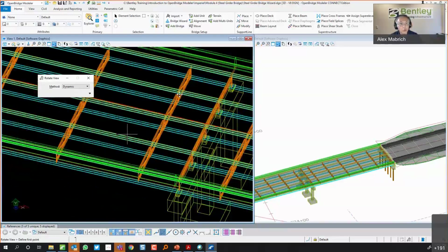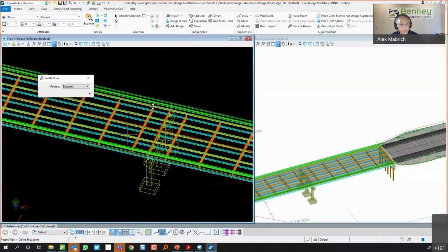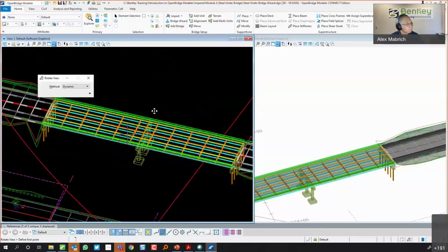The other option is to go to the library, and under the name I used, X-Frame1, update the dimensions. When I close the library, the software will know that X-Frame1 in the library, which is being used here, was updated, and since it's the same name, it will just update the bridge automatically. Okay, so that is the question that Steve answered in the chat window.